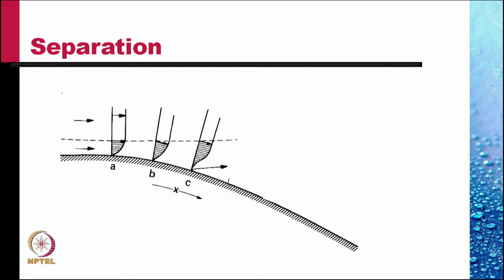The fluid in the boundary layer close to the plate, not exactly at the plate, but close to the plate, is tending to be about 0. And a little later, because of more increasing pressure, the flow reverses. The flow starts flowing in the backward direction near the plate.